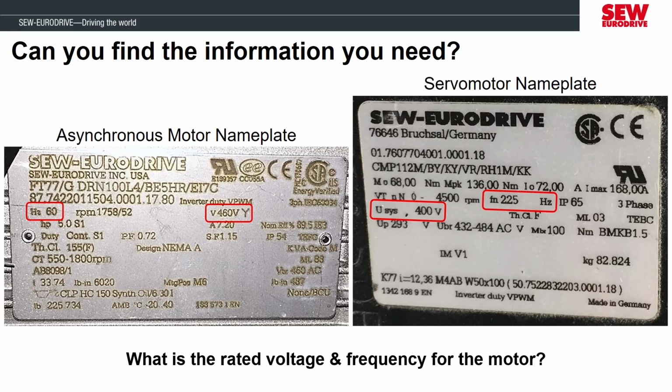You may notice that the standard motor has its volts and hertz units placed before the value, and the servo has its units placed after the value. This is just the way some nameplates are designed. The units can be spaced slightly away from the value or can be placed before it, but the corresponding unit is always printed horizontally with a value, so you do have to scan left and right to find the proper unit if it's not directly beside it. Here's the next question.